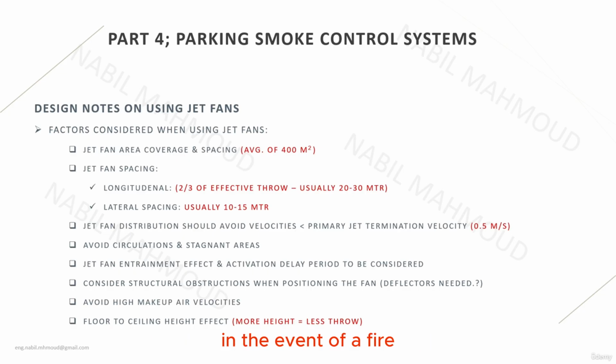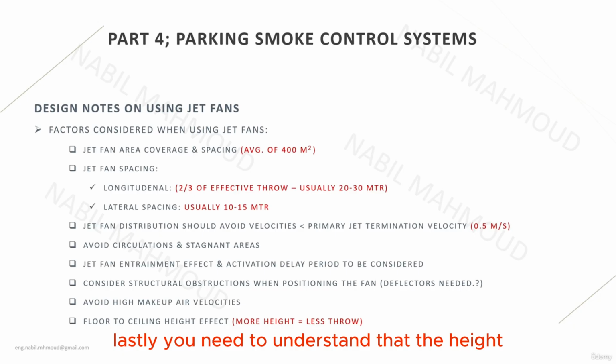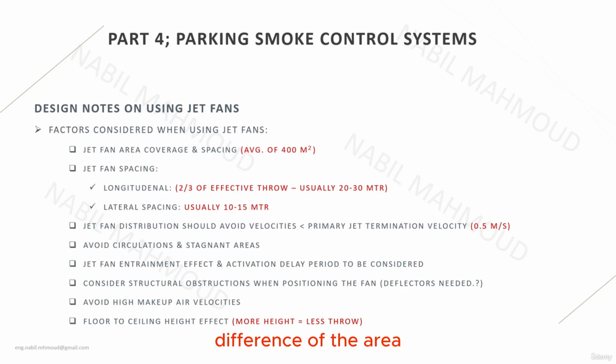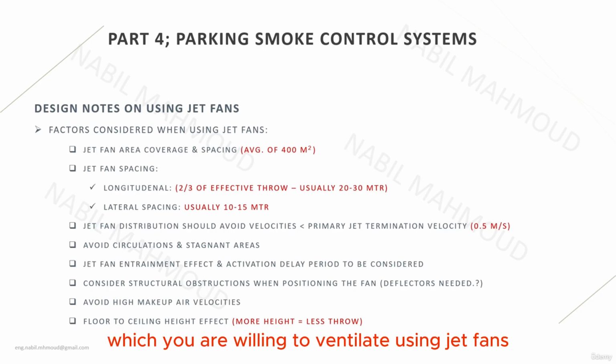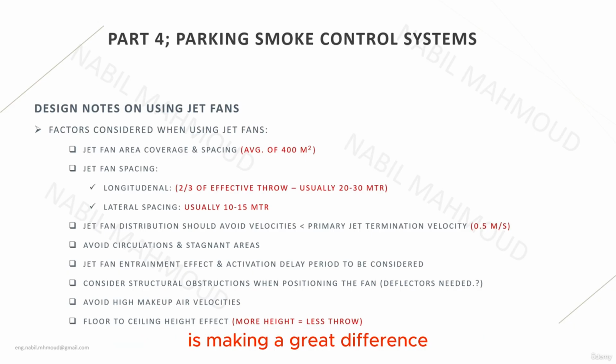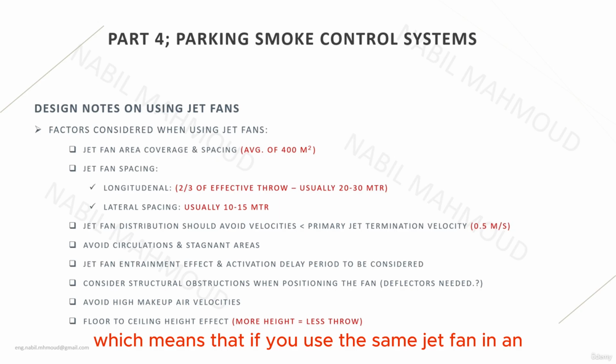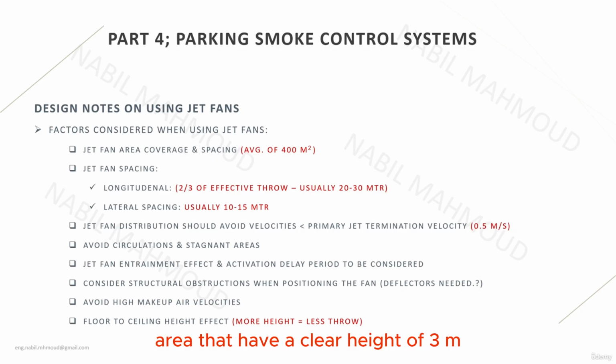in the event of a fire. Lastly, you need to understand that the height of the area which you are willing to ventilate using jet fans makes a great difference to the performance of the fan, which means that if you use the same jet fan in an area that has a clear height of 3 meters, it will not be the same as if you are using the jet fan in an area of a clear height of 2 meters, and it will not be the same if you are using the jet fan in a space that has a clear height of 4 meters.